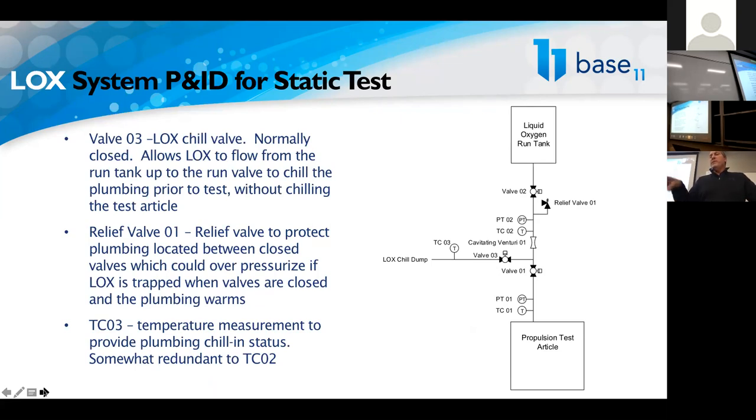What we have done here is, cryogenic relief valves at pressure are challenging, in our experience, to have them work exactly the same all the time. So most of the time we will put the relief valve on a little bit of standoff plumbing, so that unless the relief valve is cracking and opening and allowing flow, it's going to remain in ambient condition.